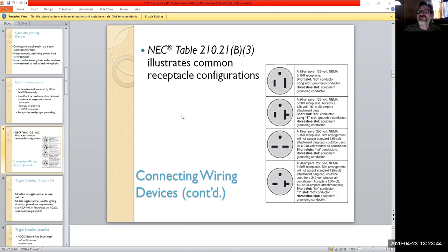If you notice, the top plug is a very typical 15 amp one. But if you do have stuff where you're going to expect to run 20 amp stuff, for some odd reason, maybe they have a receptacle where they're going to have a dedicated space heater or something goofy like that, you could end up where you have the one with a side spade.